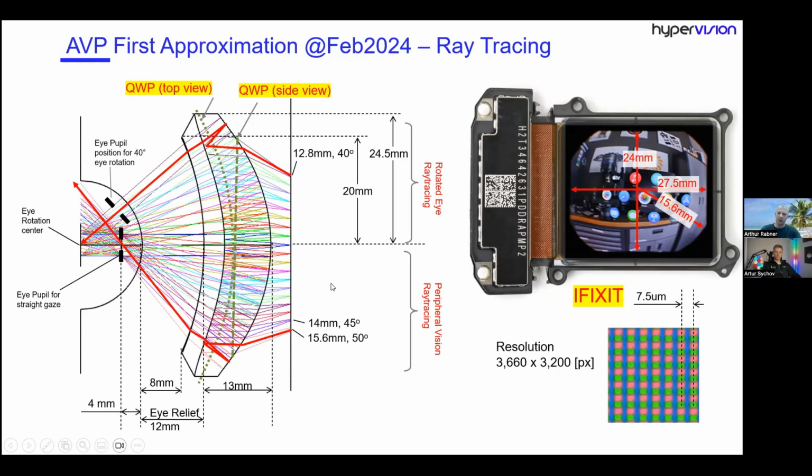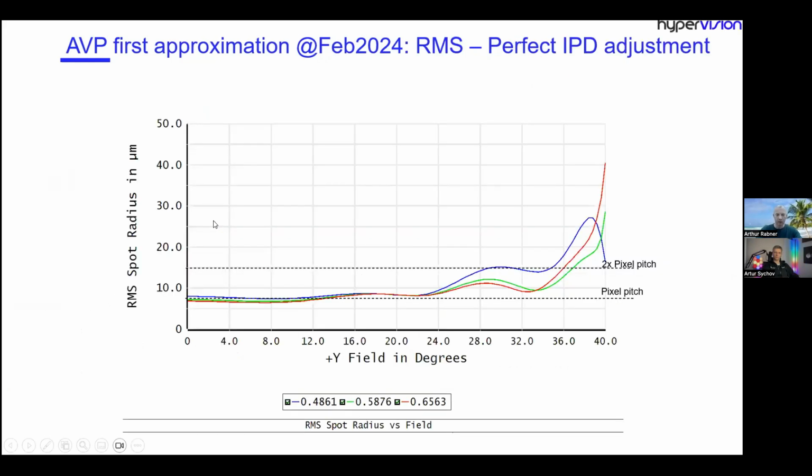We ran optimization only for 2 hours, and as I said, the thickness of the division between lenses is a little bit different from the real model, but I will present the results of this modeling. One of the most important parameters is the RMS spot size in microns versus the view angle. And what you see here...